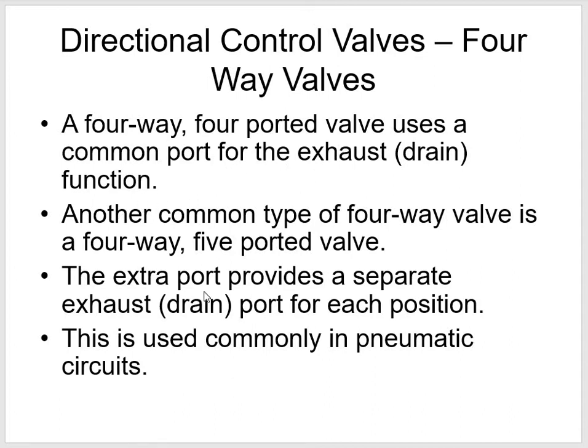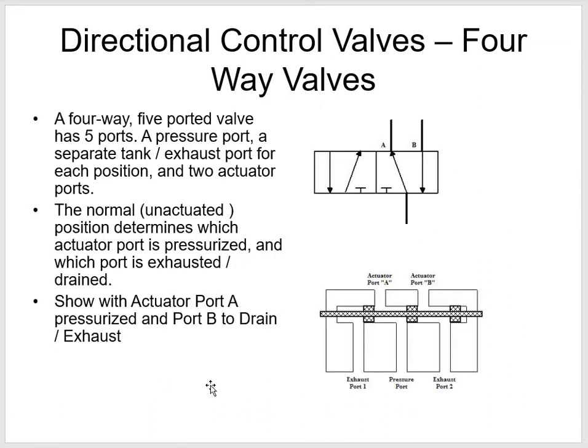So let's see, okay, the ones that we have on our board are four-way valves, but they're five-ported valves, and we will see what the extra port provides. And it says commonly used in pneumatic circuits, and of course that's what we'll be working with. So here, a four-way, five-ported valve. Here you can see it has 5 ports in it, or 5 openings.